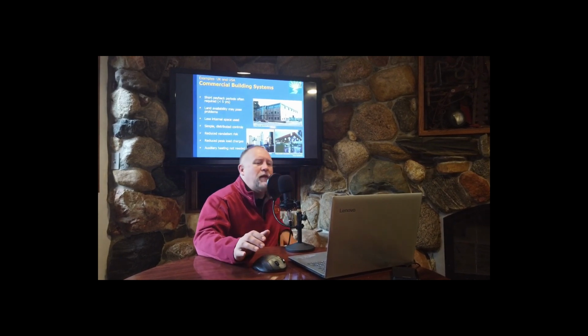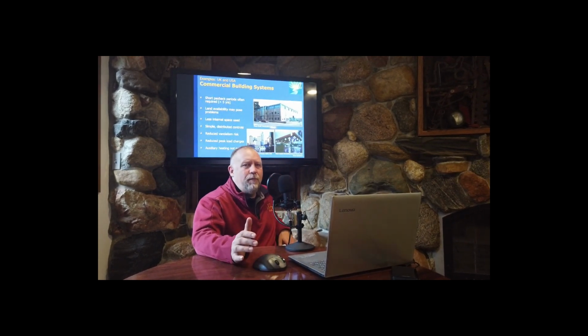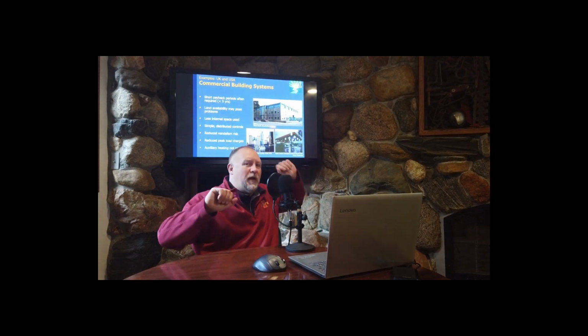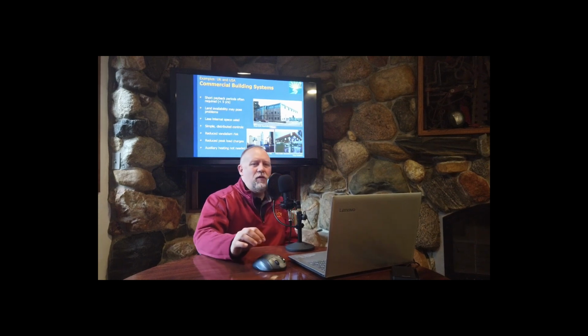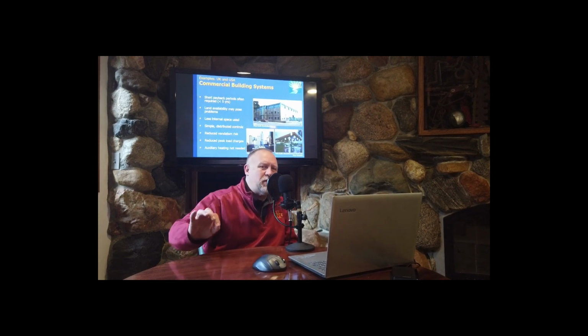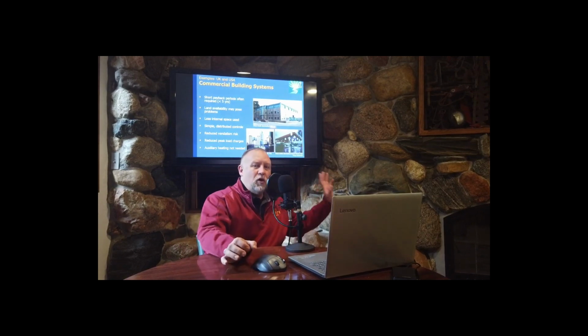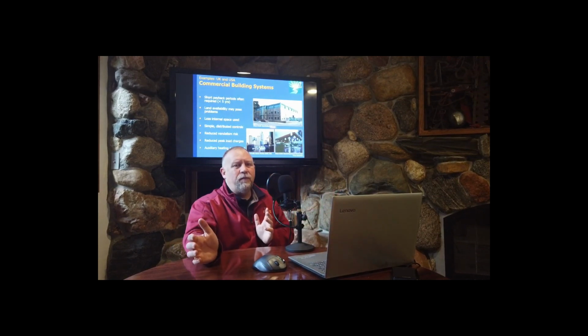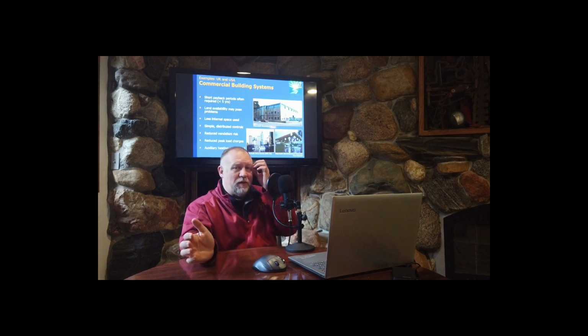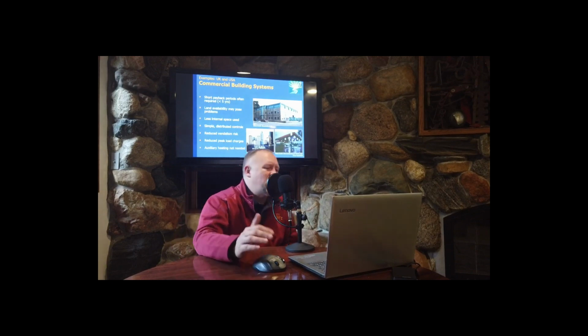It's actually kind of small. In a commercial building, those geothermal heat pumps are going to be up in the plenum space and attached to a little bit of ductwork. So you lose less space in the building and you use less visible space outside the building. Remember the cooling towers from the chiller system? You don't see anything from the geothermal system. All those tubes are buried under the ground, so you don't see them.